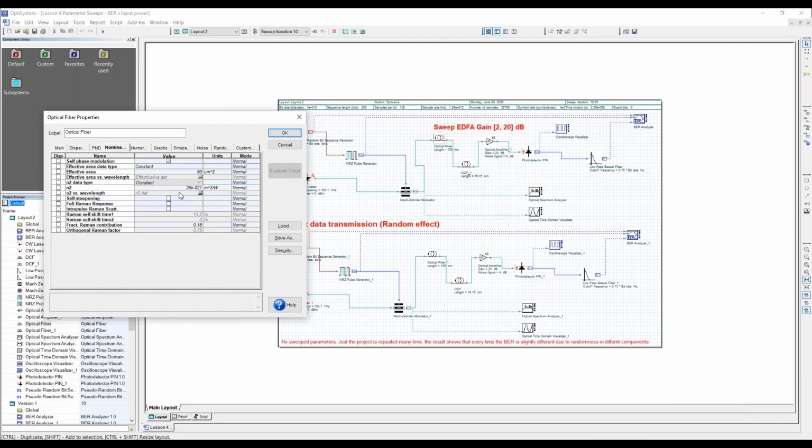As mentioned yesterday, in one of the libraries there are lots of files describing different types of fibers and their parameters, so you can download these files and use them, for example, in the calculation if you have DWDM systems where you have multiple wavelengths and you need to look into each wavelength's performance separately.